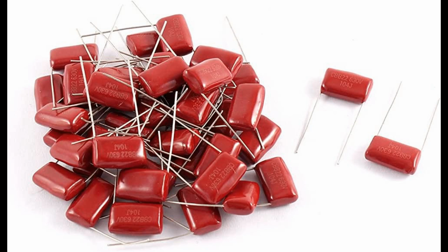2. Lower capacitance per volume. Low energy density. Film capacitors generally have a lower capacitance per unit volume compared to electrolytic capacitors. For high capacitance requirements, in the microfarad range or above, film capacitors need to be much larger than their electrolytic counterparts. This limits their use in applications where large capacitance is needed in a compact form factor, such as in power supply filtering or energy storage.